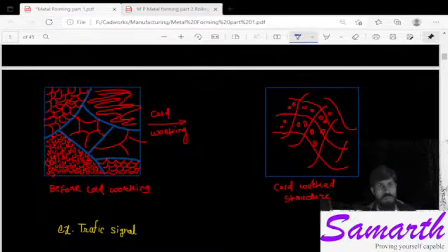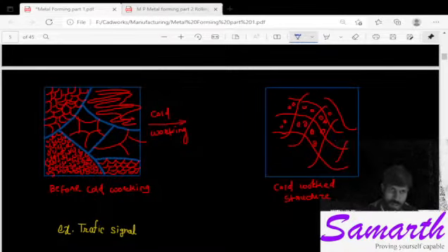So to solve this problem, what we will do is heat the particular material up to the recrystallization temperature. After the cold working procedure, here you can see the grain boundaries come closer. Here you can see more grain boundaries than in this figure. That means they came closer to each other and no further movement of the grain boundaries is possible. So again we will heat this material up to the recrystallization temperature.